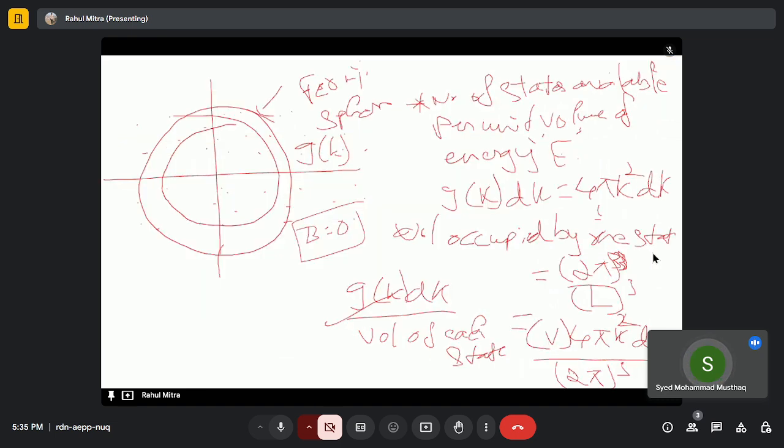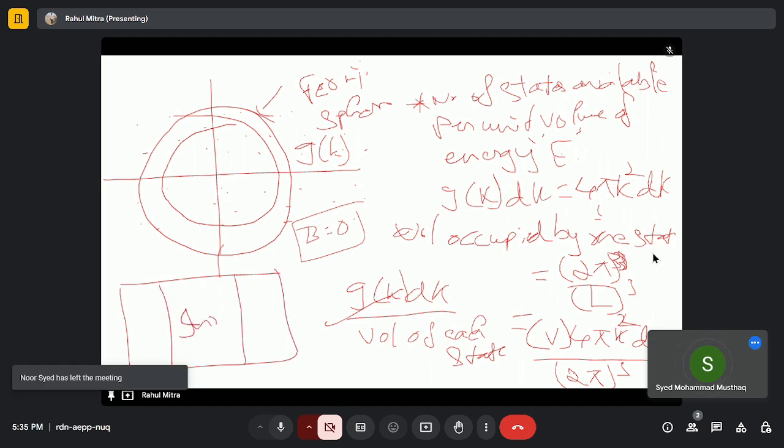Let me show you how it looks. Suppose this is my metal, this is my insulator, this is my metal, metal 1, 2, and I am applying the voltage here. If I raise the Fermi energy, then the electron can tunnel from one to another. So that is where they are used. Electron tunneling can also be used to develop field effect transistors, right? FETs made from quantum dots.